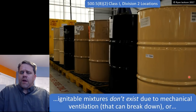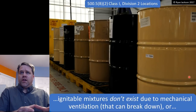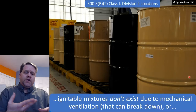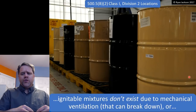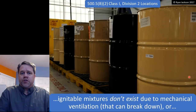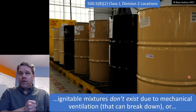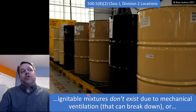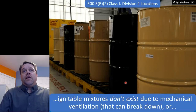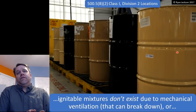We mentioned upper and lower flammable limits. I have a room that would normally be a Class 1 Division 1 location. But I also design a ventilation system, and I exhaust some air and I bring in some fresh air to lower the likelihood of having an ignitable mixture. Well, if that ventilation equipment was to break down, then we would have an ignitable mixture, wouldn't we? So if the ignitable mixture does not exist because of mechanical ventilation, then I'm going to call it a Class 1 Division 2 location, because again, if two things go wrong in a Class 1 Division 2 location, then I can have an explosion.